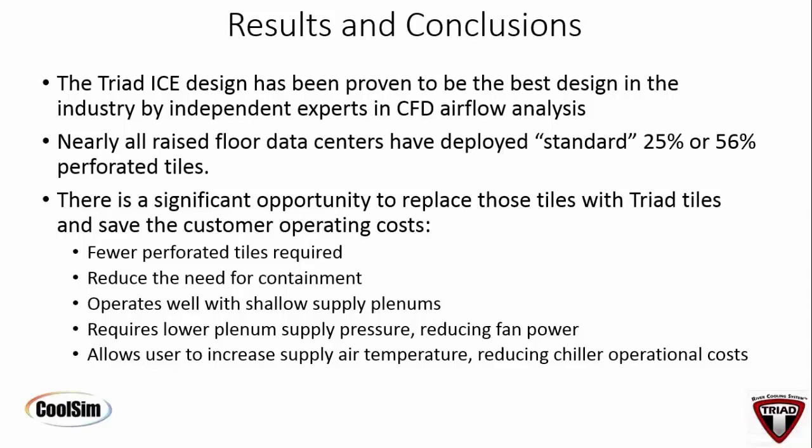Yeah, a big part of this is the science of heat transference, and you asked where I came from. The design was to start from the face of the servers and ask what's restricting. We've got plenty of cold air. We've all known that for a long time. So where's the breakdown? The breakdown is in the design of the airflow panel itself, and what the geometry needed to change in order to make it effective. Yep. So you can run the triad with lower plenum pressure, lower fan power, increased air temp. It's going to help the chiller.